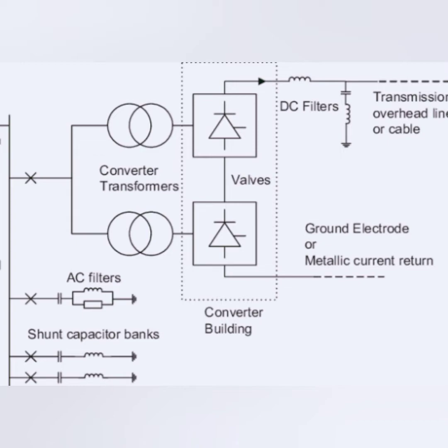We will see the particular thyristor valves, the valves which convert your AC to DC. So this is your converter transformer, star delta and star star converter transformer. In here we have thyristor valves, which is a series of thyristors connected with your converter transformer for converting this AC to DC supply in your HVDC station. This is one of the best examples for thyristors used in your substations.